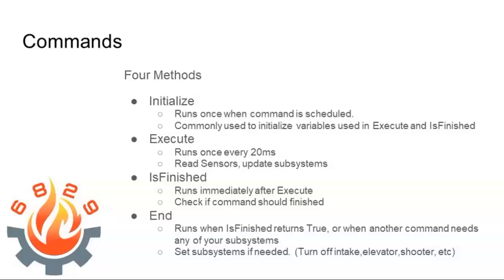My current value is 4,000. I'm not done, right? It should be simple logic tests in there. Have I met whatever condition this command has? Every time a command is running, it's going to do execute, is finished, and then moves on to the next command's execute, is finished. It's always doing that loop, remember, 20 milliseconds.